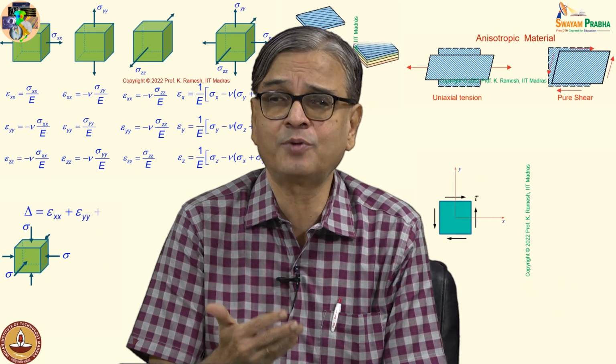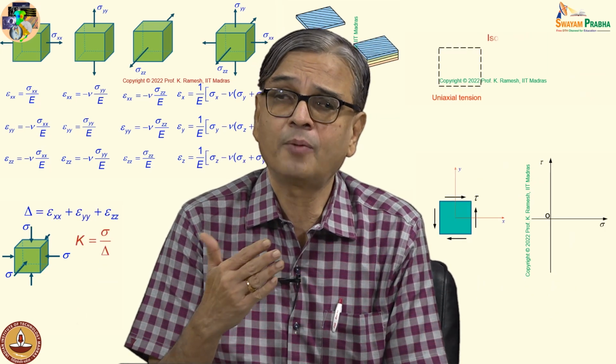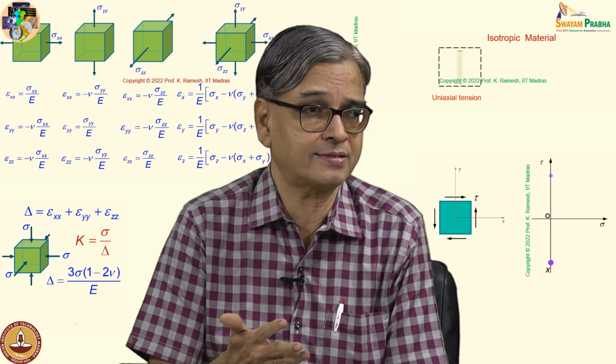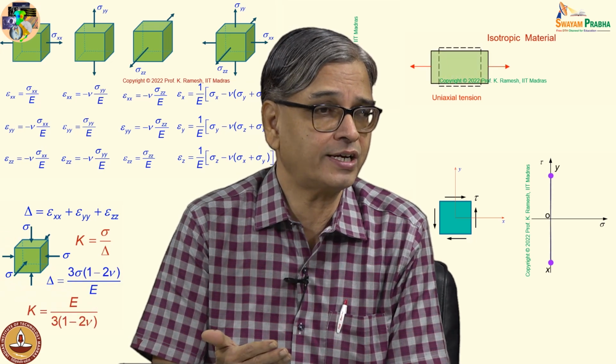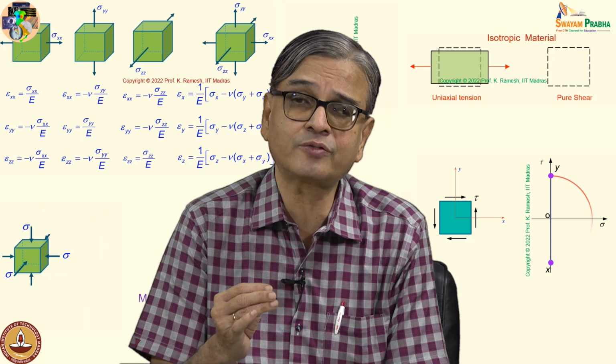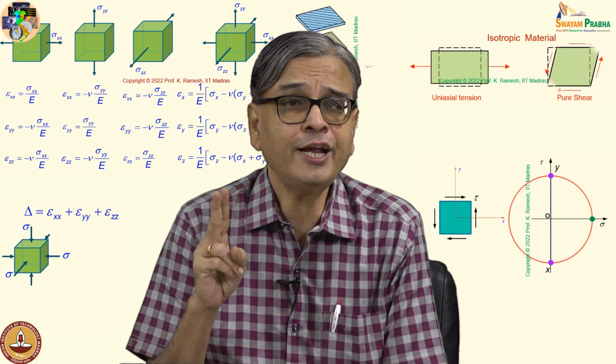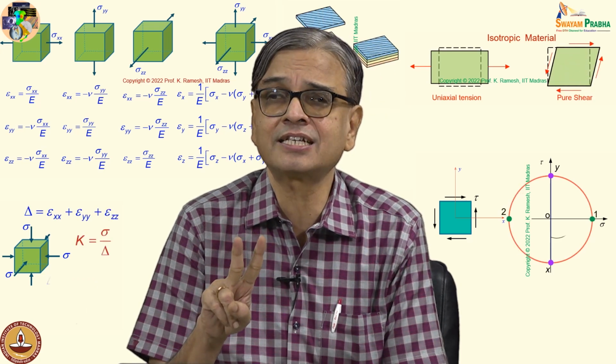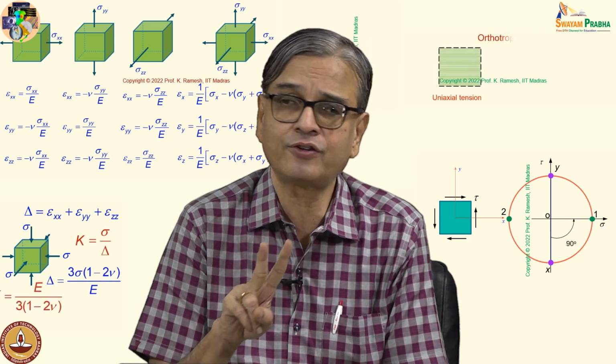You may give Young's modulus and Poisson ratio, or bulk modulus and shear modulus. You can find out all other quantities. An isotropic material requires only any two of the 4 elastic constants that we have brought into focus.